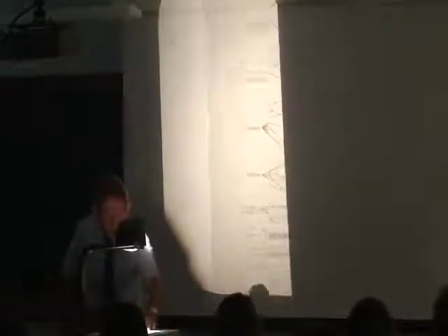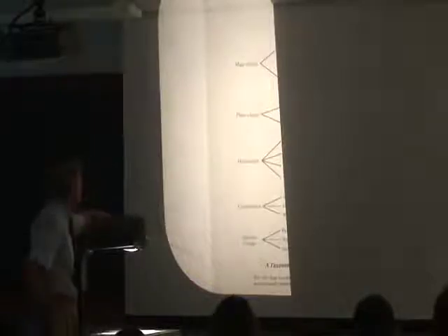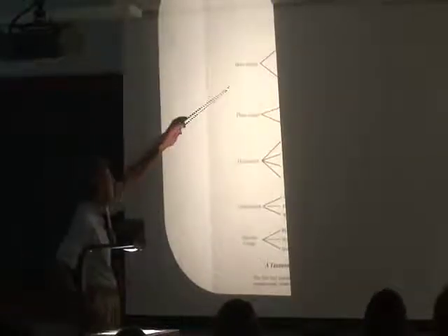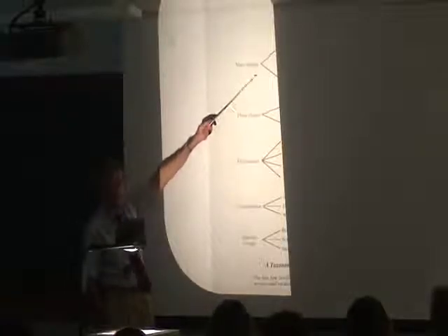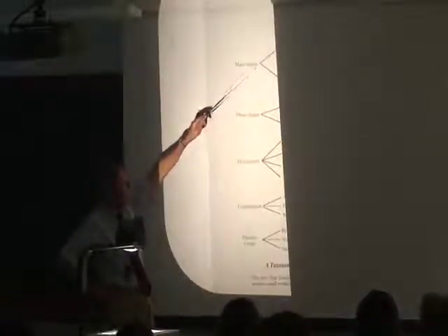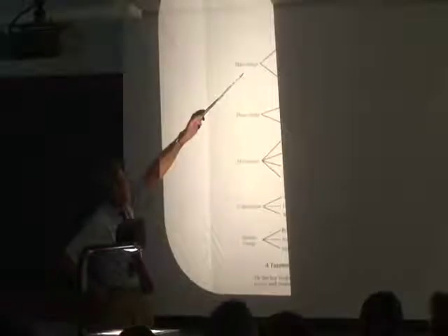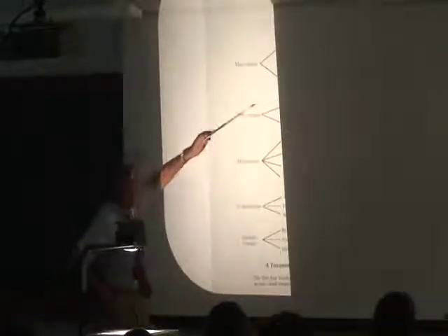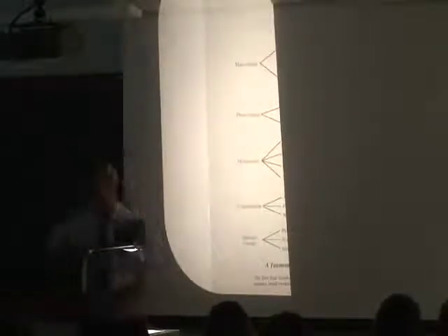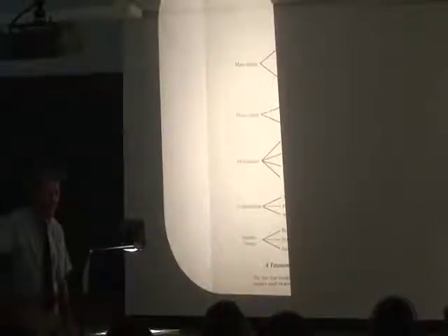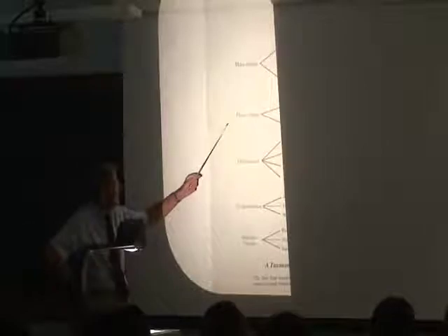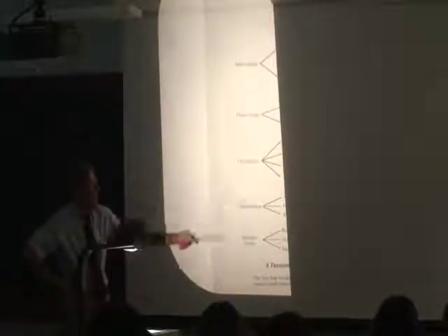And starting up here, you have some changes which are mass change processes. And machining goes in here. You see it, you machine stuff away and you take away mass apart. And you have additive processes too. Phase change processes. This is when you start with a liquid, you put it in a mold and it solidifies and becomes a solid. You change the phase of the material. Deformation. Lots of these.